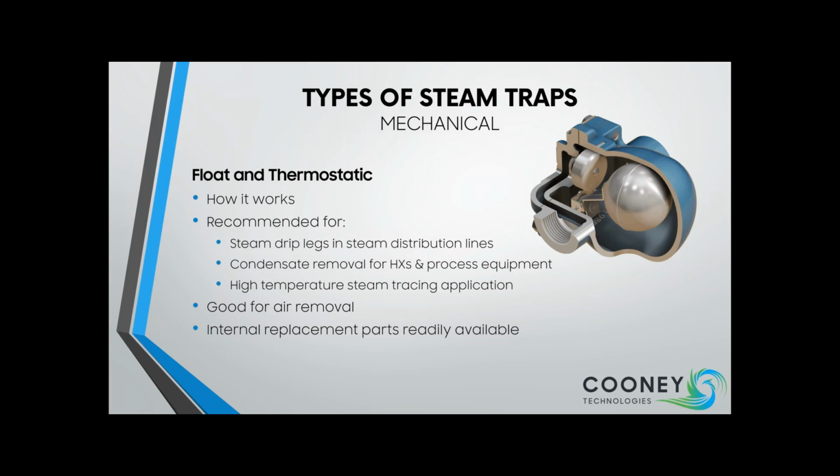The F&T trap also has an internal thermostatic air vent near the top of the body inside that allows air evacuation from the steam system through the trap. F&T traps are usually recommended for use on steam main drip legs, condensate removal in heat exchangers and process equipment, and also steam tracing applications.